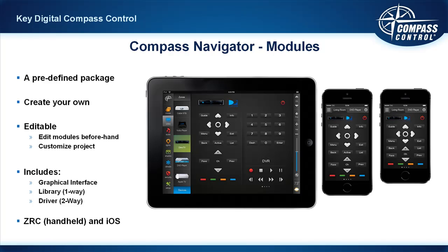Okay, now, the modular-based programming method was introduced really with single zone applications in mind. Single zone. Why? Because everything operates off of a zone connectivity tree. You'll build, and we'll teach you how here in C1, a zone connectivity tree. So that, as you see in this image, if I press the DirecTV button, Compass Control is actually going to execute automatically a macro to select that selected source, in this case, the DirecTV.